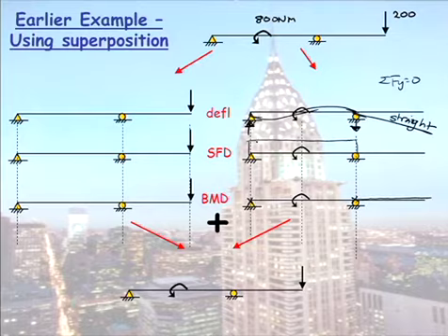Now, we have a constant positive slope because our shear force is constant and positive. Therefore, we have a sloping down bending moment diagram. So based on it being 0 at the left, it slopes down. Based on it being 0 at the right, it has to slope up. So there is my bending moment diagram. Make sense? Kind of? Think about it.